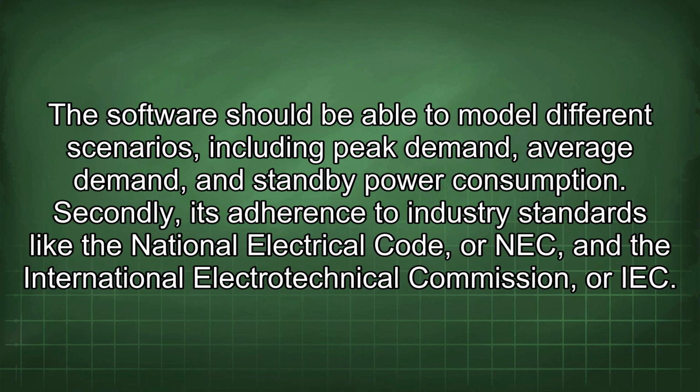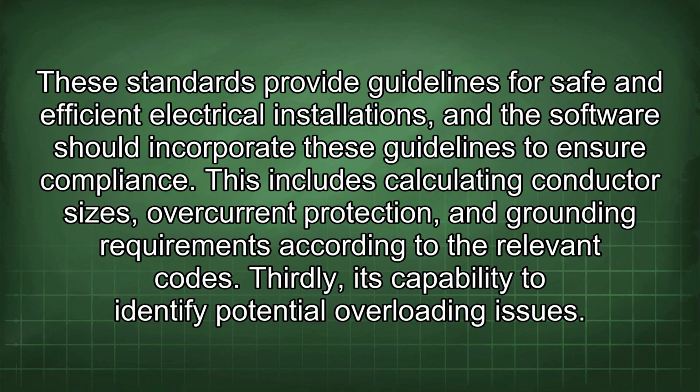Secondly, its adherence to industry standards like the National Electrical Code, or NEC, and the International Electrotechnical Commission, or IEC. These standards provide guidelines for safe and efficient electrical installations, and the software should incorporate these guidelines to ensure compliance. This includes calculating conductor sizes, overcurrent protection, and grounding requirements according to the relevant codes.